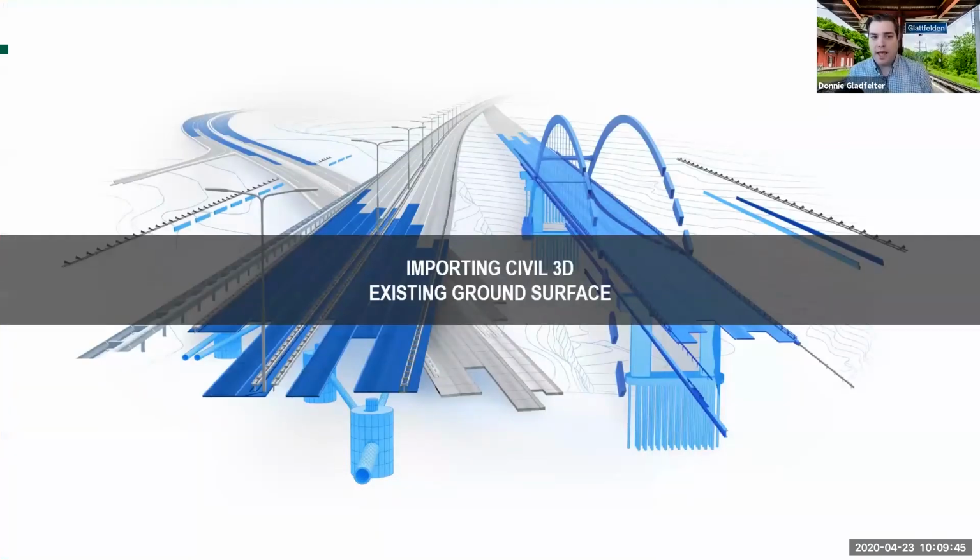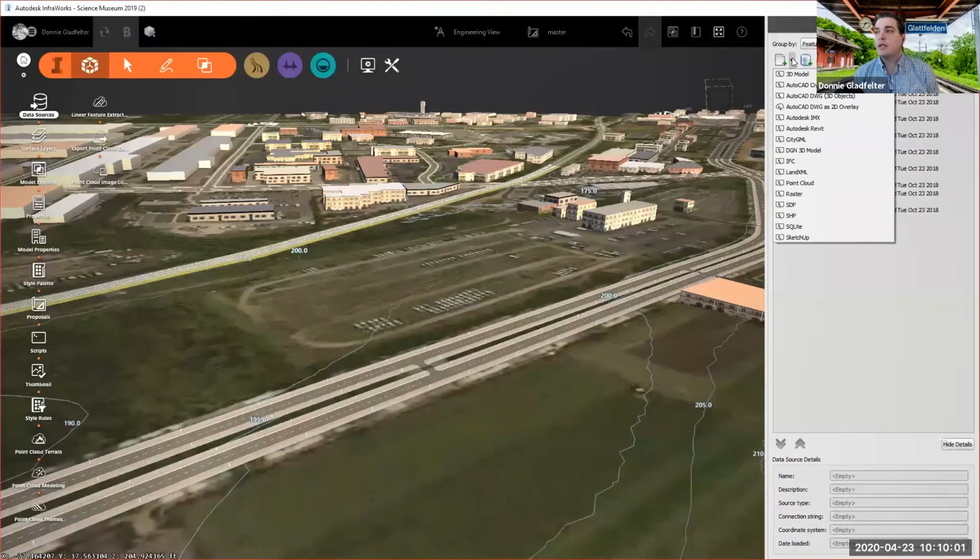Now, that base file is pretty great, but the data that I have for my project is probably a bit more accurate. So this is where I like to begin augmenting that initial Model Builder model by using my actual project data. I mentioned, or you saw a bit earlier, that we exported our surface as a LandXML, and we used that LandXML to bring it into Revit.